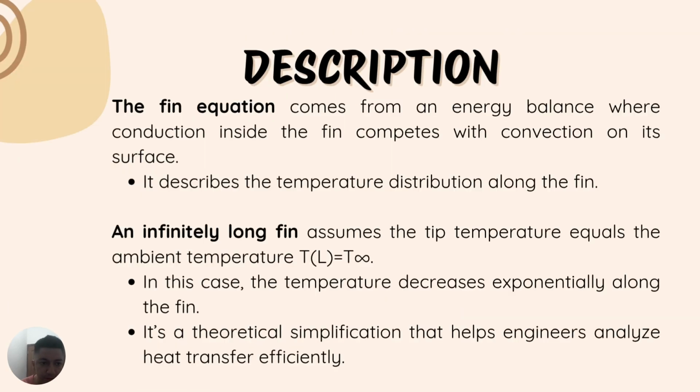We have the description. First, the fin equation comes from an energy balance where conduction competes with convection. It describes the temperature distribution along the fin. Infinitely long fin: the tip temperature equals the ambient temperature, T equals T infinity. The temperature decreases exponentially along the fin. It is a theoretical simplification that helps engineers analyze heat transfer efficiently.